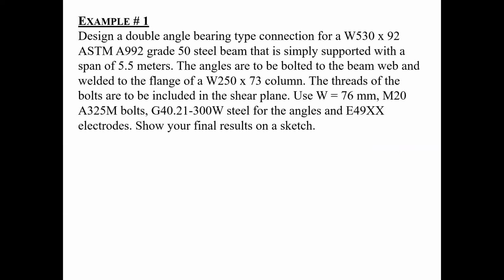I'm also trying to, you know, steer you. In this case here, like I said, if I was doing this, I would use 3/4 inch bolt. I wouldn't use M20, but I'm doing M20 so that you guys can realize where you get the value from the table. Now, A325 bolts is what the table is based on. So therefore, in your specification, you're going to have to say that you have A325M bolts because I'm using metric.